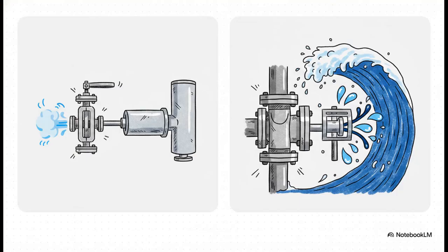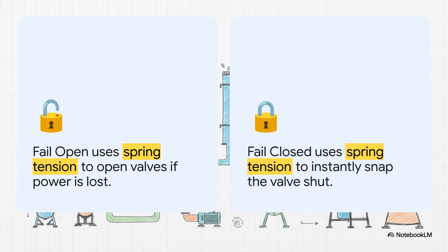So, the plant basically relies on two main types of muscle to physically crank open or slam shut these heavy metal doors. Pneumatic actuators are your standard everyday workhorses. They use compressed air to push a diaphragm or a piston. But when the plant needs to force a massive valve shut against a raging, high-pressure tsunami of liquid, it flexes its hydraulic fluid muscles. Since liquid simply can't be compressed, hydraulic actuators deliver way higher brute force without losing any energy to compression.